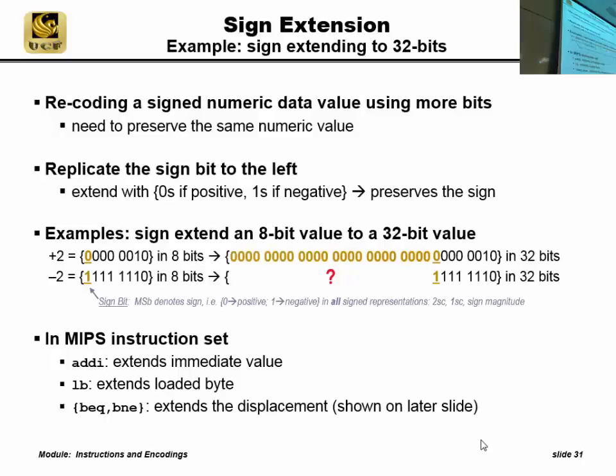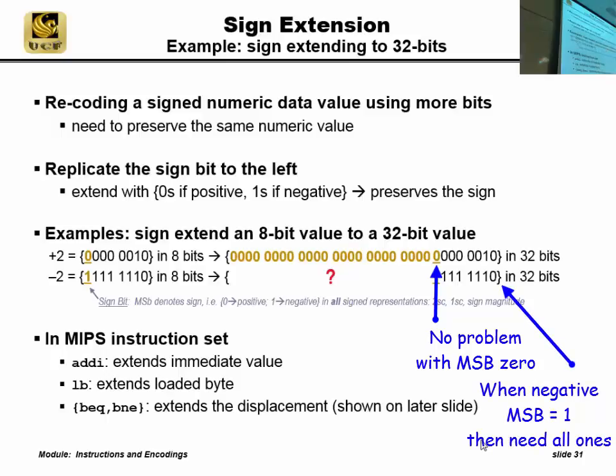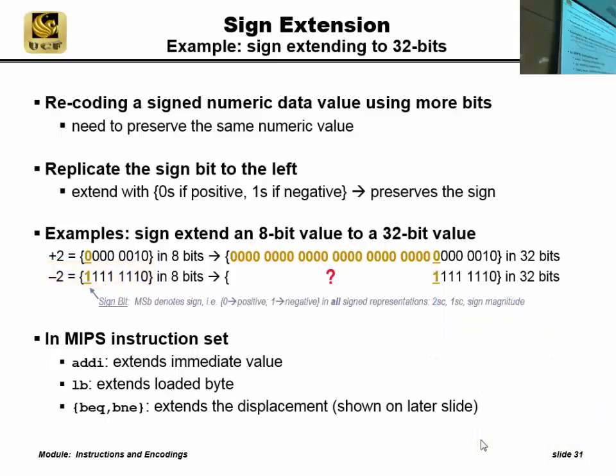And you're going to say, why would I want to do that? If the sensor is sending you a byte and the processor needs to put it into a register, as 8 goes to 32 bits, we have to populate the missing bits somehow. If you just put 0, it works fine for positive, but what if coming from the sensor was -2? Is this -2? Yeah, because -1 is what? All 1s. I take away 1, I get this. It's -2. So, suppose we just put all 0s here and convert to 32 bits. Did we convert to 32 bits? No. We changed the sign, right? We need all 1s here.